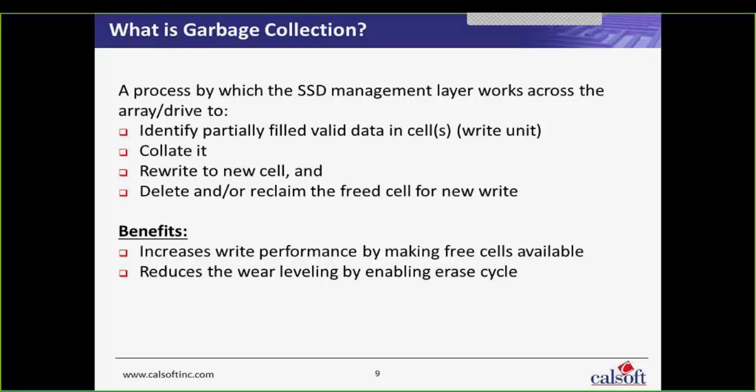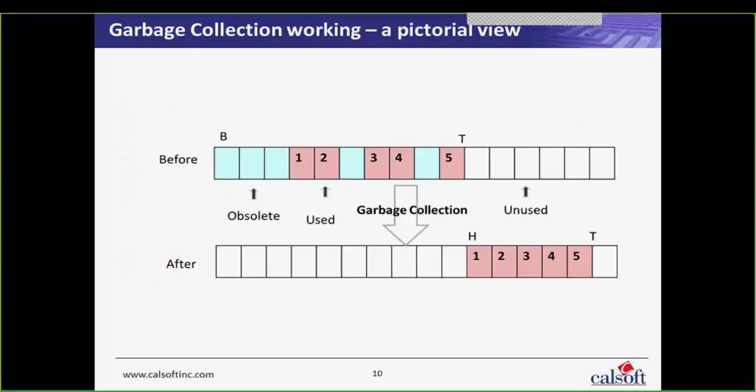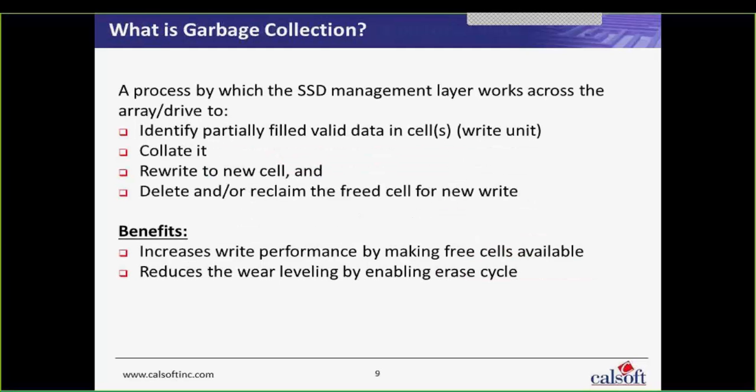This is again something that has to do with the kind of implementation that a particular vendor has. Wear leveling normally goes into two different categories, which are dynamic and static wear leveling. Just to give you a gist of it, dynamic wear leveling basically pools erase blocks and selects the block with the lowest erase count for the next write. Static wear leveling selects the target block with the lowest overall erase count and erases the block if necessary, writes new data to the block, and ensures that blocks of static data are moved when their block erase count is below a certain threshold.